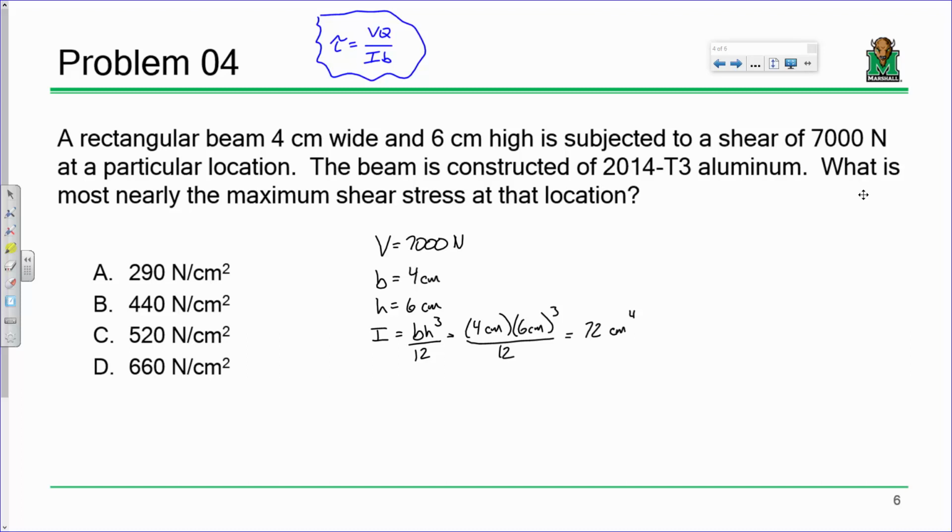Now, first off, I want to make sure that everybody is clear as to where shear stresses come from. I need something I can bend. So what's happening with shear stresses is as follows. Here's a beam. If I bend that beam, it's fairly easy to bend. Why is it easy to bend? Because this isn't one beam. It's 100 really tiny beams. Each one of these.